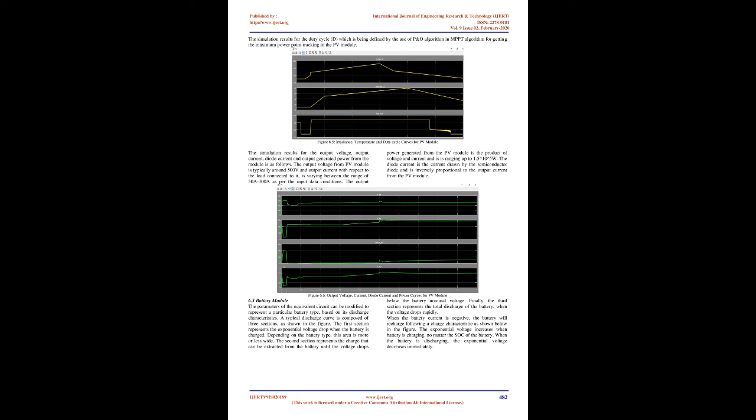Chapter 5. Simulink implementations. The implementation is very flexible because of this ease of modification. In fact, it is so flexible that a script could prompt a user for the input datasheet values for the solar module he or she wants to simulate, together with other optional variables like the number of PV modules in a string, and the script can define the variables necessary and run a simulation with available irradiance data.